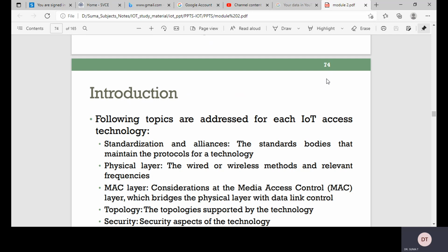The payload size for IEEE 802.15.4 is 127 bytes, and it requires the IPv6 payload with a minimum MTU of 1280 bytes to be fragmented.